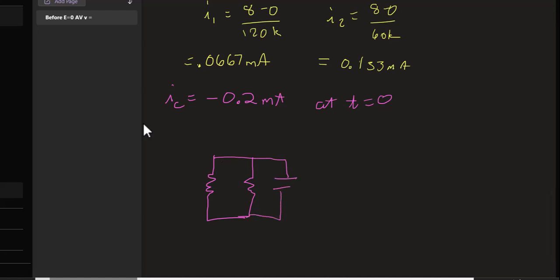There's no current source, there's no voltage source. And so when we started, our capacitor was charged. As the current flows, every time the current flows through a resistor, the resistor absorbs power. It's absorbing energy. And so the energy that was stored in the capacitor gets dissipated by the resistors in the form of heat. The energy that it had was 1/2 CV squared. It was 1/2 times 100 times 10 to the minus 6 times 8 squared.